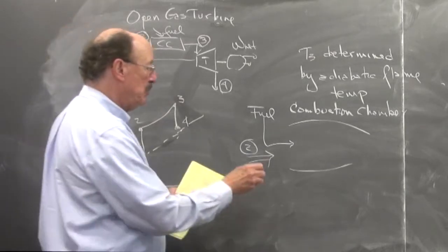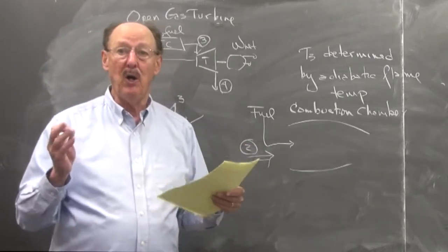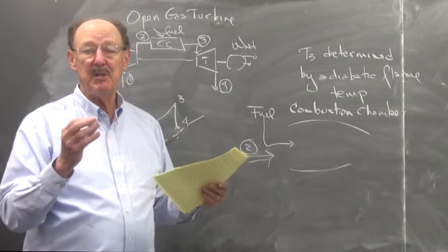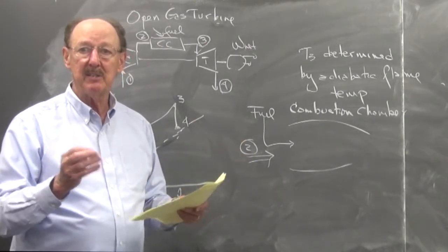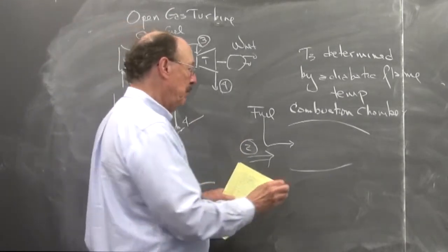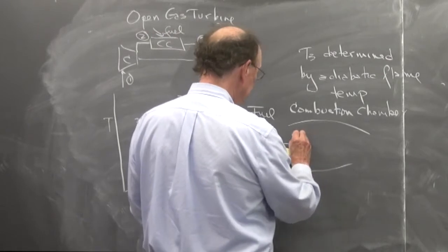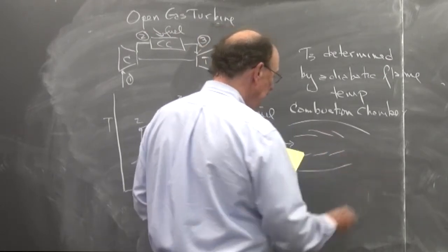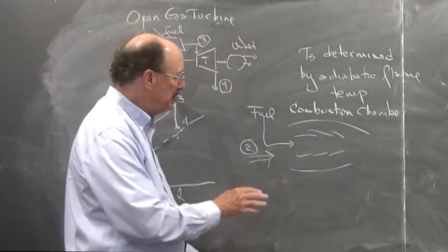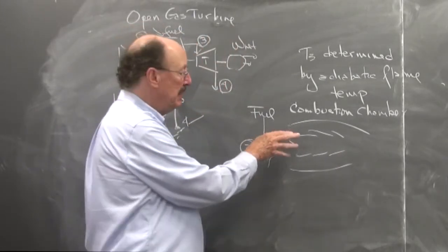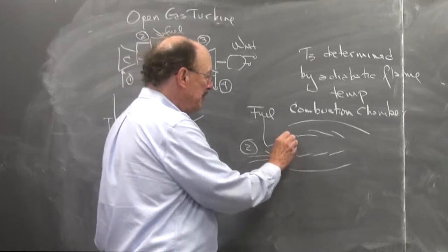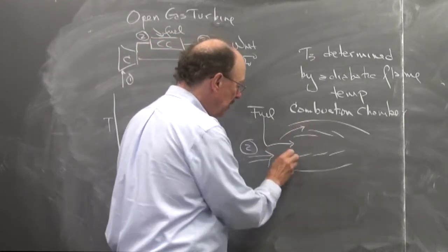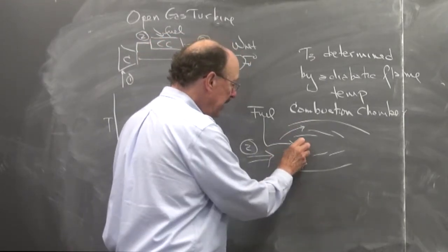It's going to mix with the fuel, but I don't want all the air because we're dealing with maybe 300% theoretical air, so there's a lot of air. So what we do is we have some of the air bypasses. So in the combustion chamber itself, sometimes there are holes, there are fins, so what happens is I have bypass air, and I have air going in here.